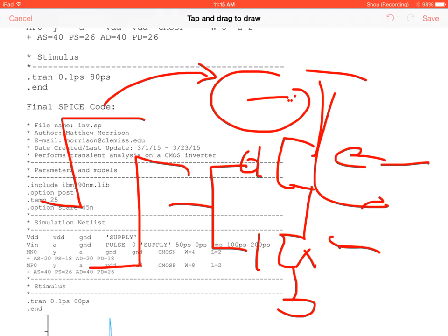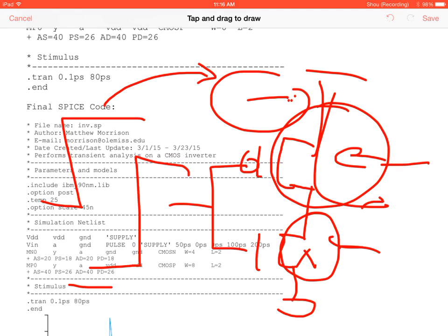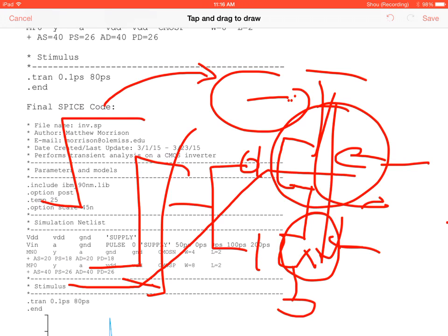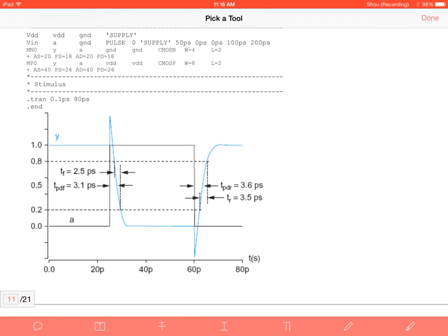So what's happened is we immediately spike to the opposing condition that's still high. So we have an instance where this is turning on, it's still on, but it's trying to turn off, and this is trying to turn on. And if you don't regulate that properly, what you should be doing is you should have some sort of step response, giving it that opportunity so you're not creating that extra channel of current. If you create an instance where you're going through both channels, that's where you're going to get these really high power spikes. And so when we actually show the simulation, that's what's actually going on here.